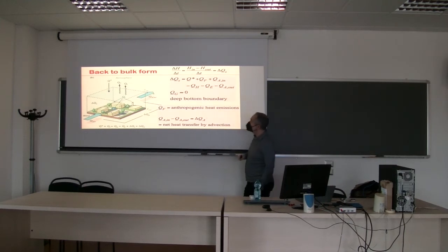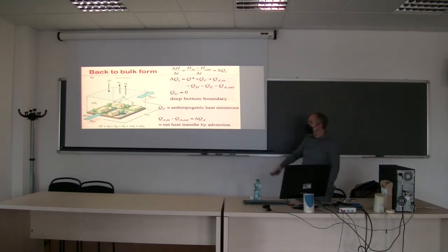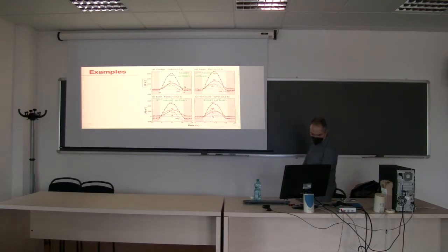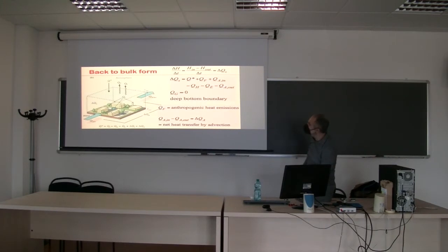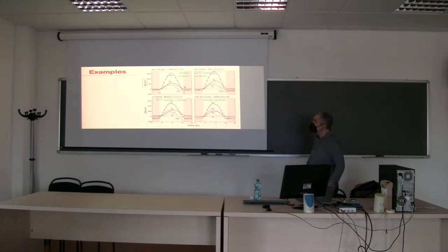You also know that we have to add the term QF with it, which is anthropogenic heating. So chimneys, cars, building heating, all that contributes to emissions that we are creating into this control volume. So this now also has to be included, and we call this QF. So notice that we started with a thin interface, we got a simplified one, but when you go to consider the whole city, it becomes more complex, and you have to take into account anthropogenic heat and advective terms.